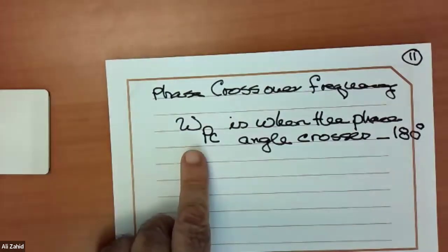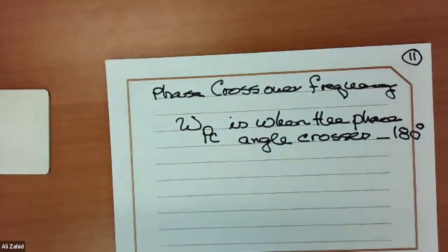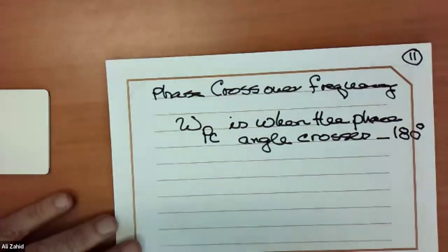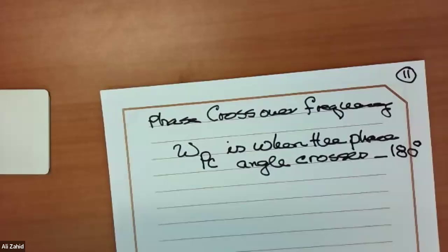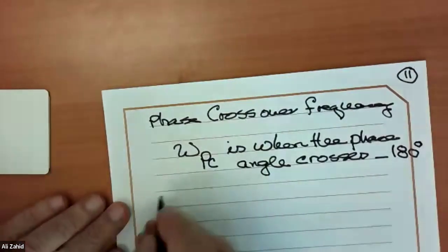Students always make the mistake when they try to find the gain margin, they use the gain crossover frequency, which is wrong. You need to use the phase crossover frequency to find the gain margin. Right. Did you get it? That makes sense, because you want to know the intersection with the real axis. That is correct.